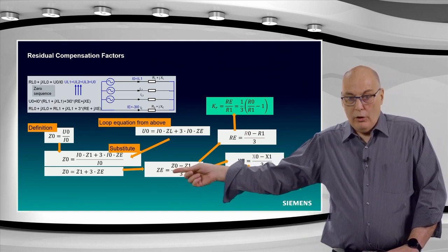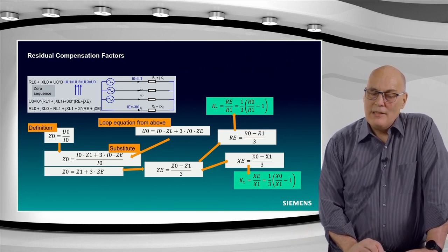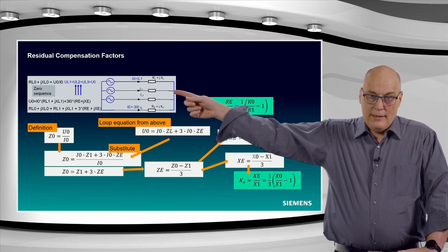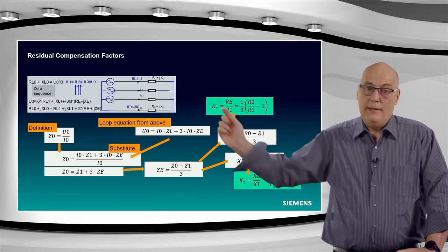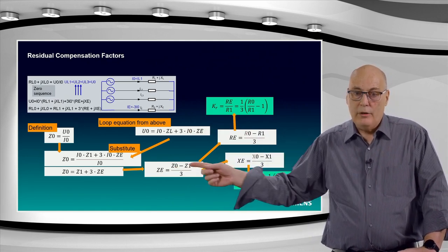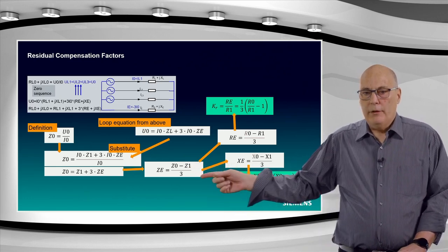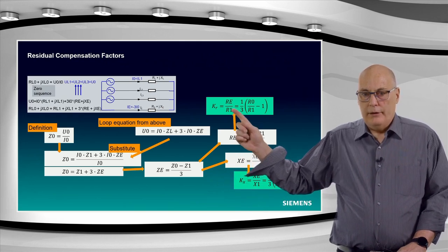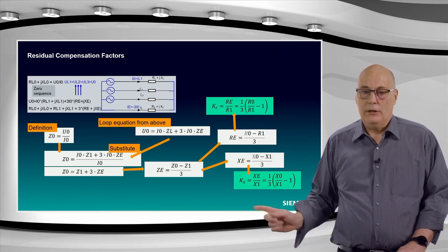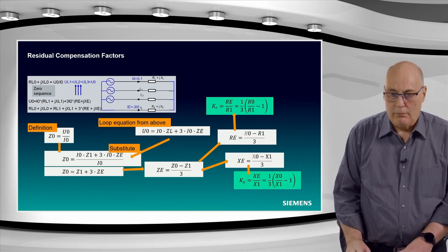Rewriting that equation, following the orange arrows, we then come to this equation here. We can then derive ZE, and this is an important thing that I wanted to say in the diagram at the top. Remember, we said this was Z1, but this is not Z0. This is ZE down here in this diagram. Be careful: to get from Z0 to ZE, you have to use this equation, Z0 minus Z1. Right, and then from there on in, we can calculate this RE, R1. Remember, R1 is the same as RL, as such, the Kx over here. And we derive these two equations from that.